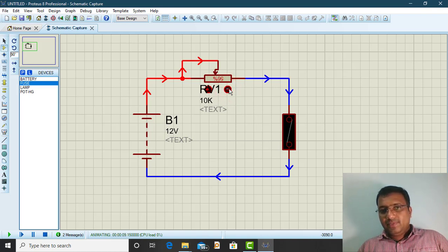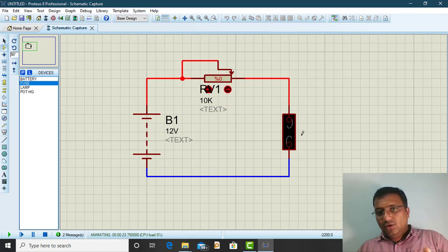At some level, the current starts flowing in the circuit, and then it's like a short circuit. When there is very low resistance, the current is heavy, as in a short circuit. Observe it. Still not. Okay, have you observed it? Once it is zero, the fuse is blown off because it is a short circuit, like the positive terminal of a battery connected to the negative terminal, because you are making this resistance zero. Because of this the fuse goes off, and then this circuit gets disconnected. Okay, so this is about the fuse.